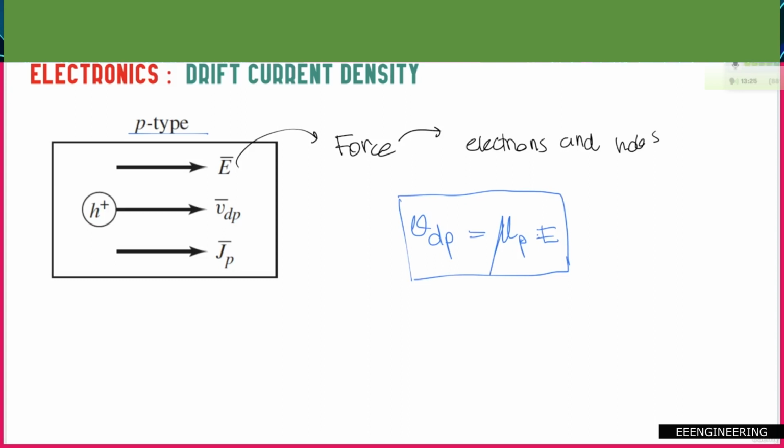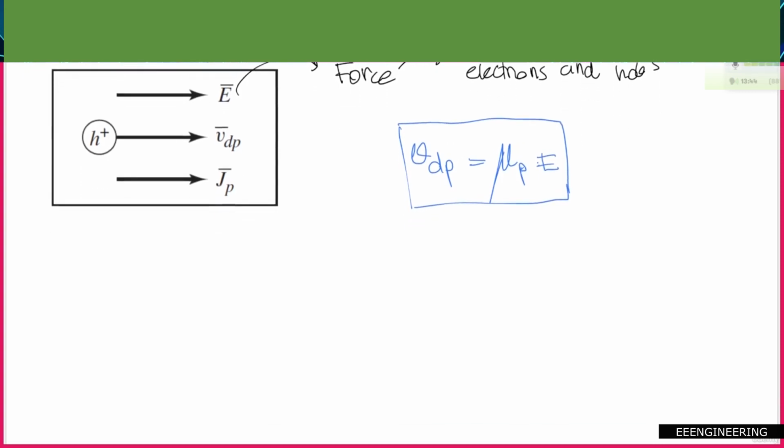And the logic we have in here is that the positive sign indicates electric field and velocity are in the same direction, which you can easily see on the figure. And this hole drift also produces a drift current density, which is, by the way, denoted by Jp, just like Jn. So that Jp is going to be equal to, which is a quite similar formula to what we found earlier for an N-type material, E times N times, alright, that's a mistake.